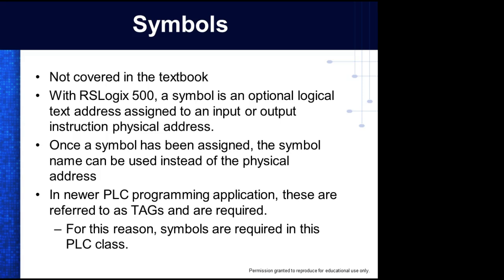Once a symbol has been assigned, the symbol name can be used instead of a physical address. In your PLC application, these are referred to as tags, and they are required. It keeps you from duplicating addresses. There are a lot of features on there. For this reason, symbols are required in this class.